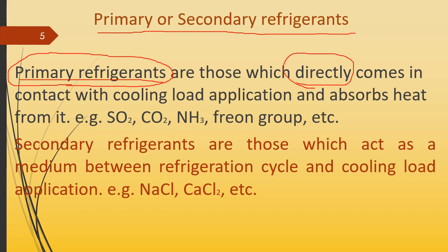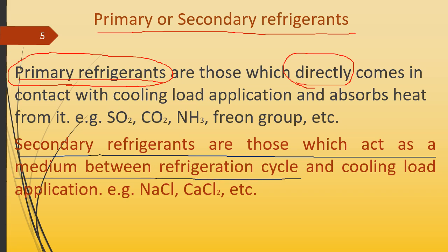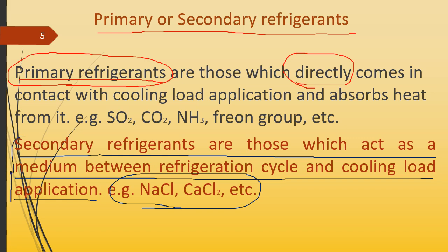But if we talk about secondary refrigerants, they are those which act as a medium between the refrigeration cycle and the cooling load application. So these do not directly come in contact with the cooling load application like primary refrigerants. The examples you can see here are NaCl, CaCl2, etc., which are secondary refrigerants. There are some applications where we have to go for secondary refrigerants, so we will discuss secondary refrigerants in detail at a later stage.